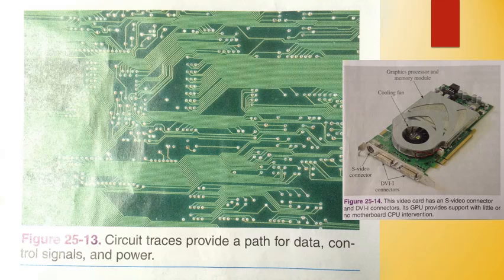The two main types of slots encountered are Industry Standard Architecture, or ISA, and Peripheral Component Interconnect, or PCI. The most common ones for light commercial and residential use are PCIe, that is PCI Express. ISA is one of the oldest types of slots and was developed many years ago. It is not manufactured into boards any longer for wide distribution. They are still manufactured for, again, industrial use.